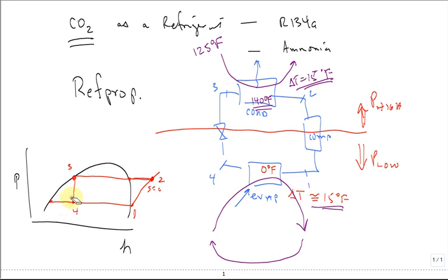See, so when I come into the evaporator at state 4, I don't have quality of 0, I have quality of 20, 30, 40%, whatever the quality is. True? So take this concept and try to sketch on this diagram that's generated with RefProp that I'm going to give you a copy of. Sketch what type of pressures we need for the high pressure side and what type of pressure we need for the low pressure side. We still only have high pressure and low pressure. Okay? So I'm going to pause and then pass this.